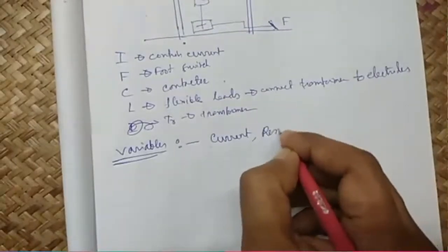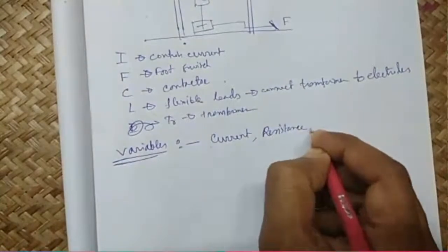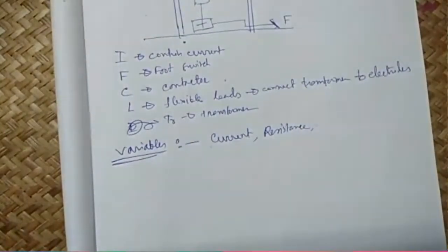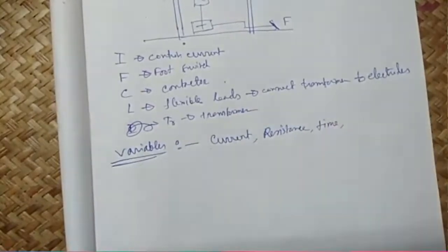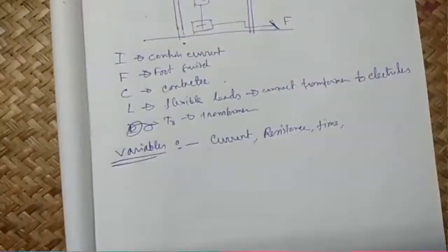The resistance is not much to control here. The time is also a very important criterion. You have to provide a fraction of a second through which the current will pass. Because if the time is higher, the heat produced will be higher, and there will be a hole in the sheet. When you try to join, the sheet will be punched,